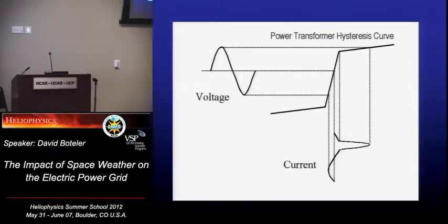What we've got there is very much a variation of this. The area inside this curve represents losses inside the transformer, so a lot of engineering design goes into reducing that. So what they've really done is they've taken that curve, and it's very thin there and sharpened off at the edges. So here's the normal operating region. And then if the transformer saturates, you're taking it around this knee and you're up in this region. This represents the saturation region of the transformer.